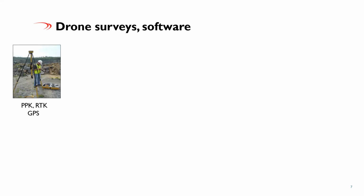In this case, you can see this is a portable system that we have here. It could be a permanent mount as well. Typically, a lot of your larger mining open pit operations may already have GPS running at those sites, but we find a lot of the smaller quarries don't have that capability. So in those cases, it's very convenient to be able to have a portable base station that we can bring into a site, set up on a hub, and be able to get accurate coordinate measurements for the site.